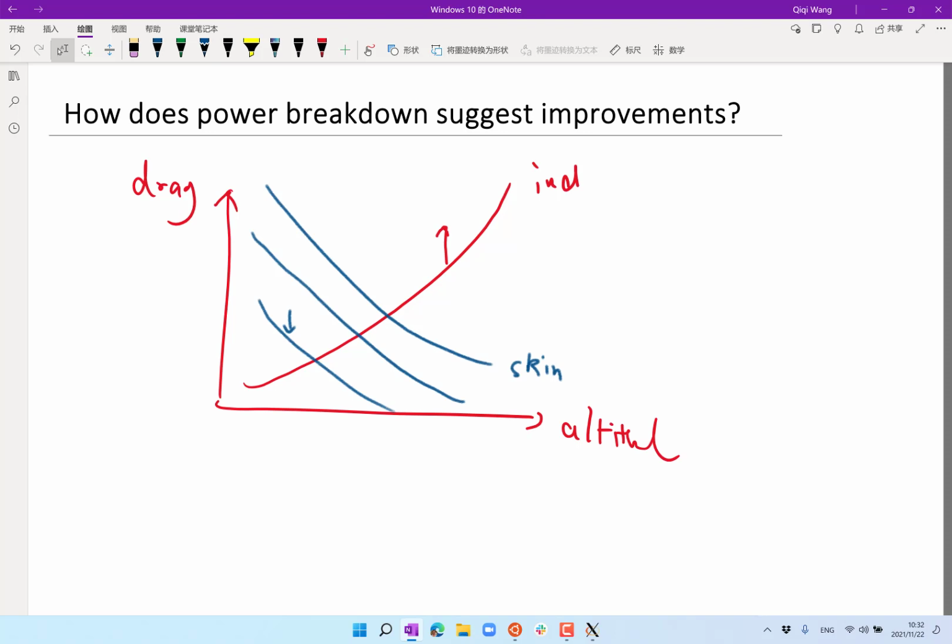And for helicopters, we're not going into the design of helicopter rotors, but one thing we can assume is that it's very difficult for a helicopter to go faster than a third of the speed of sound. Even if your rotor tip spins at the speed of sound in the forward sweep, the backward sweep is going to be only a third of the velocity at the tip.